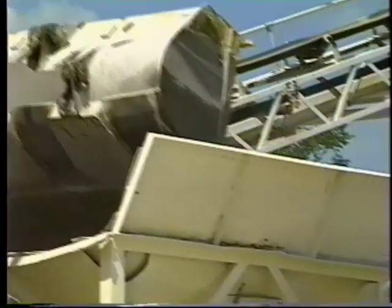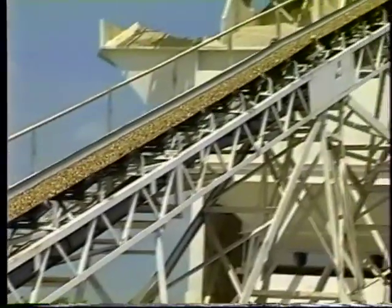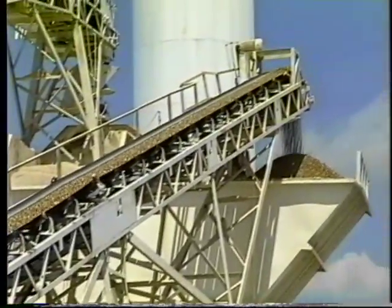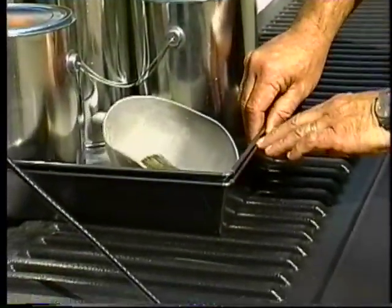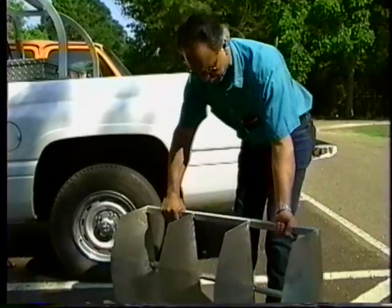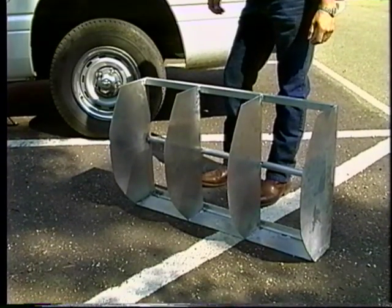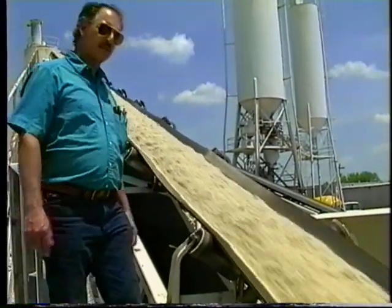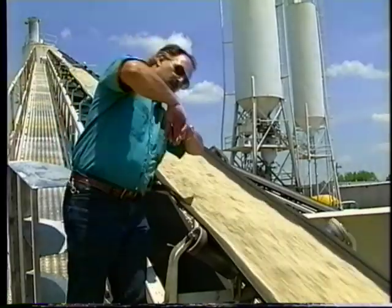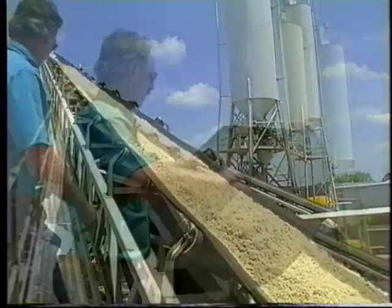The procedures for sampling from conveyor belts and bins are almost identical, so we will cover only sampling from conveyor belts. When sampling from a conveyor belt, in addition to the other sampling equipment already mentioned, you will need a scoop, brush, catch pan, and a special sampling template for the conveyor. Refer to the Sampling Aggregates, Aggregate Mixtures and Soils Handbook for the procedure for determining sampling frequency for conveyors. Once you know the required sampling frequency, wait until the flow onto the belt has stabilized and stop the belt at a randomly selected time.